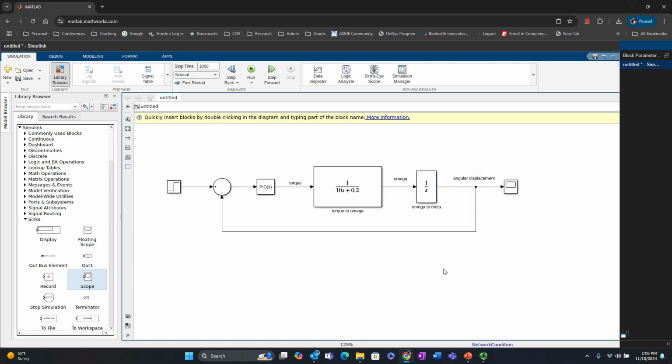The reason I split these two is as follows. What I would like to compute is the power, mechanical power. And to be able to do that, I need to multiply torque with angular speed omega. In the previous version, when these two transfer functions were combined together, omega was not really visible, only angular displacement was visible. By splitting these two transfer functions, I revealed an intermediary variable, omega, which I really need to compute the power. And so torque times omega is going to be power, so I need a product, and that should be in math.